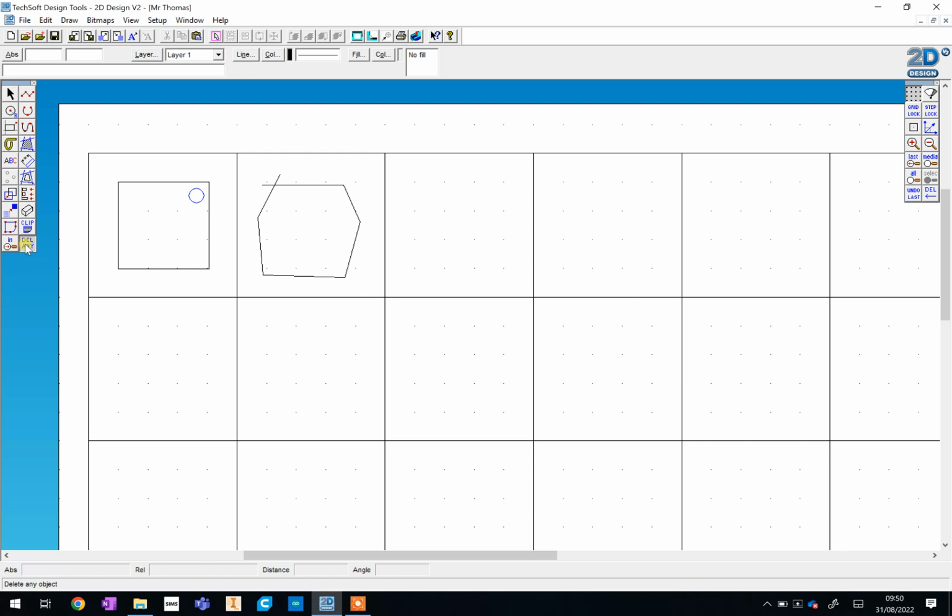If you hold down your mouse button on the delete any, move across to the next one, delete part of an object between the 2 nearest intersections, and now we can just click on those overlapping lines and we've got our shape. If you like something and you want to copy it, we can do that too. So let's say I want to copy the circle, the hole. You just select it, and then underneath here you've got the 2 squares that say copy. You can select it. To move anything, you just drag the middle square inside the shape and you can move it to wherever you like.